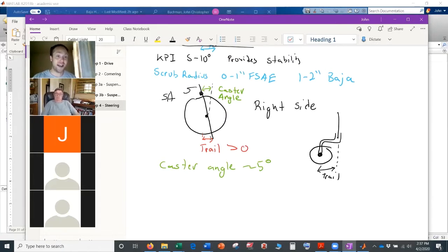So if you design your car with a big caster and end up down here, you've made a very unstable system. The tire rotates about that point and the forces can push it left and right and force it to turn. So this is really hard for the driver to hold on to because it's very unstable. So you need a little bit of positive trail, right?